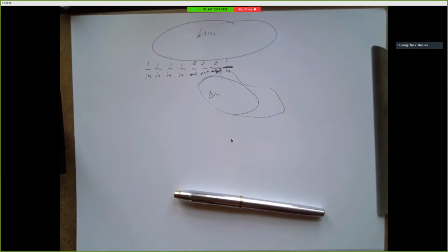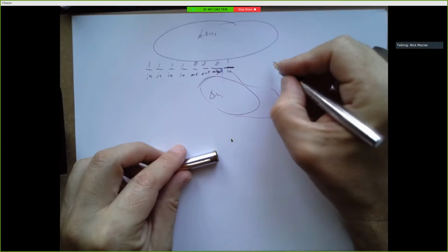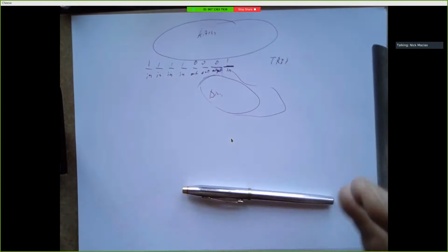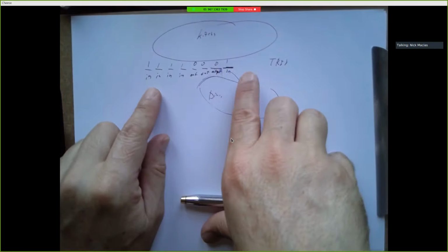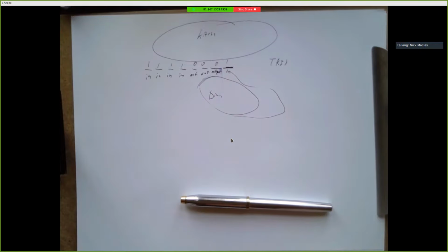And now when you want to move in and out, you use the port register, right? You use the doors. The signs, which are the tri-state registers, those are just indicators for is each of these doors, is each of these bits supposed to be used for reading in from a pin or writing out to a pin, input or output. Okay, it's a setup thing in the very beginning.